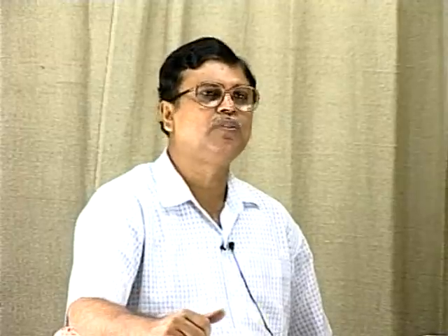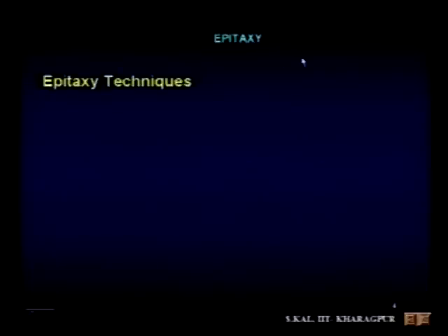And 3-5 semiconductor also, we grow heterojunction devices, there you need heteroepitaxial film. So those two, silicon germanium or the 3-5 semiconductor materials where you can grow heteroepitaxy and which will form heterojunction devices, and those devices may be used for high speed circuits particularly. Now next I will discuss on epitaxy techniques.